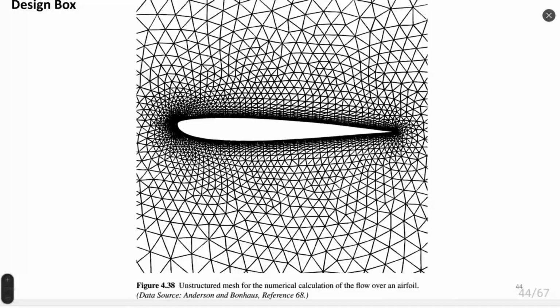Boundary layer and flow conditions inside are completely wrong, and shear stresses are completely wrong. So you cannot do evaluation from viscosity point of view and drag point of view. Here in unstructured mesh can be found same problem. So I would say that triangular mesh has to be used very carefully by specialists who know how to evaluate error associated with approximation methods.